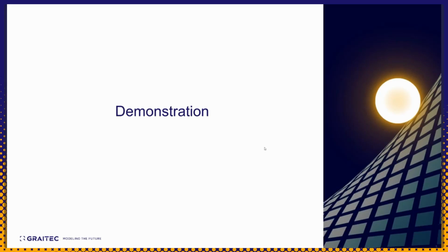Your analytical model should be properly created first before sending to Advanced Design and any structural solution, because if you have any discontinuities or offsets or eccentricities that your members are not connected, basically you cannot run a structural analysis on that. So before that, you will need to fix your analytical model inside Revit, which my colleague Ciara will show you right now. Ciara, please, thank you.